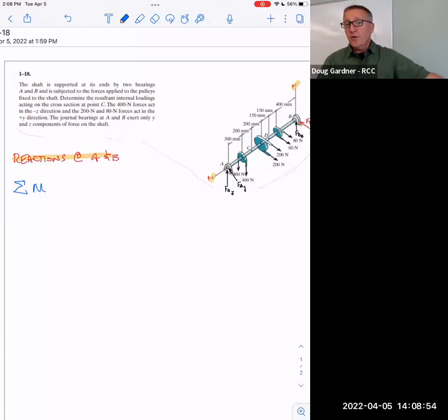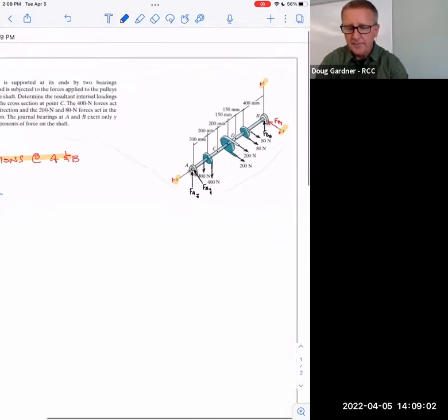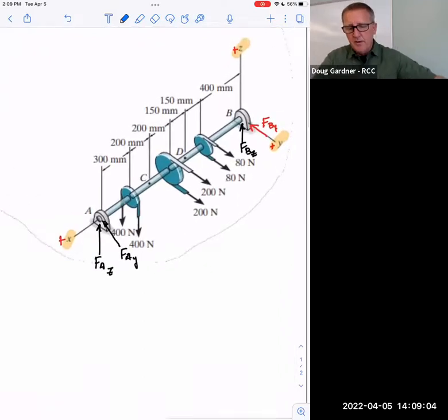So what axis would these forces, and let's consider the 400s, what axis are the 400s trying to rotate around, the X, Y, or Z? You need to be able to see that. The Y. Connor suggests the Y. Are the 400s going to cause it to spin around the Y axis, as Connor said, or is it actually the X or the Z? He's right. It's Y. Do you see that? Can you imagine it spinning with just the 400s? I'm only looking at the 400s.